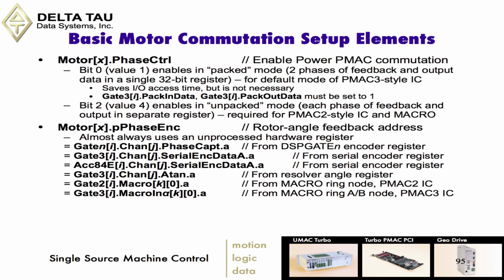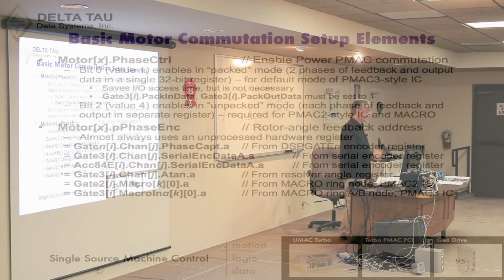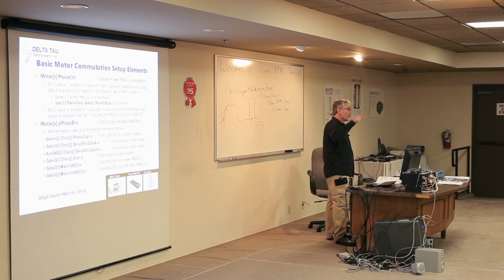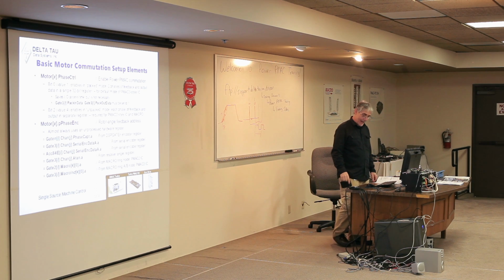Because in one revolution, both a sinusoidal encoder and a resolver give an absolute position. Another commonly used method is that some sinusoidal encoders actually have a third channel that's a single sinusoid per revolution, or they just provide a one sine per revolution output as the absolute position in one revolution of the feedback device. That's also common now.